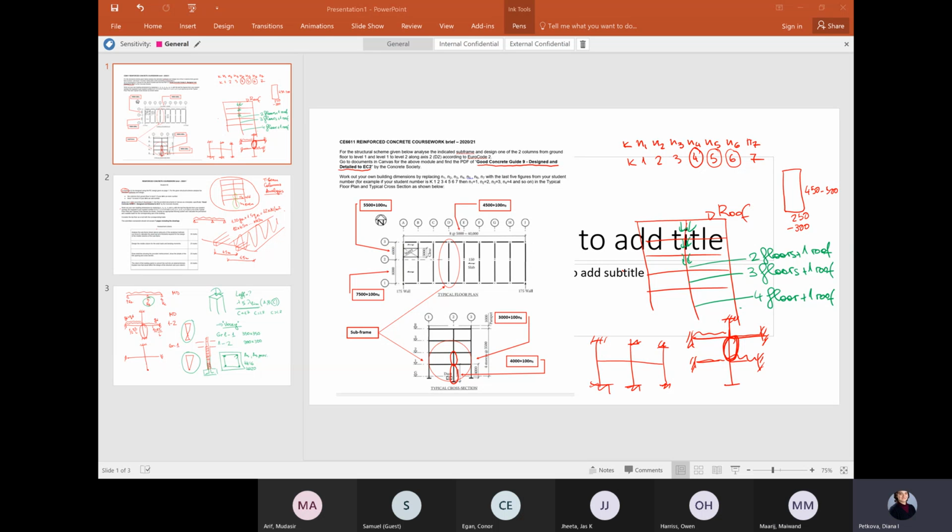Right. So looking forward to your designs. By the way, when you introduce your loads, I would prefer to see a cross section as well. So perhaps the flooring system, then screed, then the slab, then the suspended ceiling with just some characteristic loads, and then obviously the calculation of the design loads.